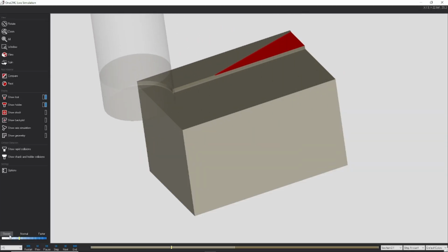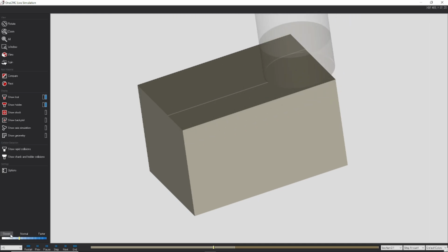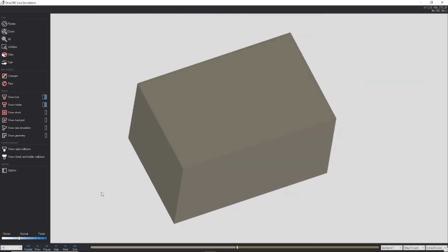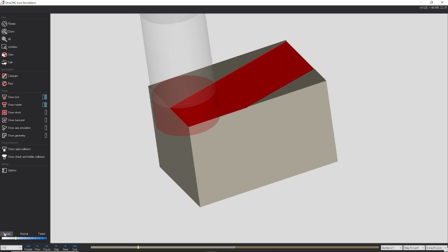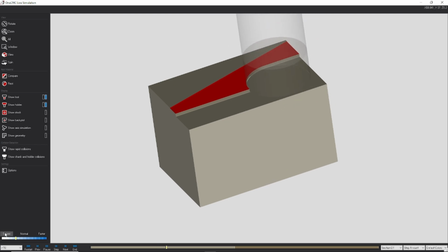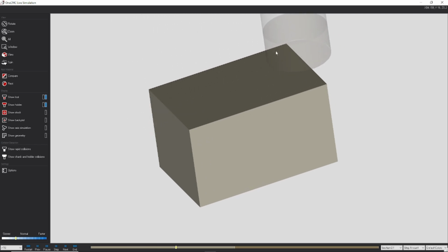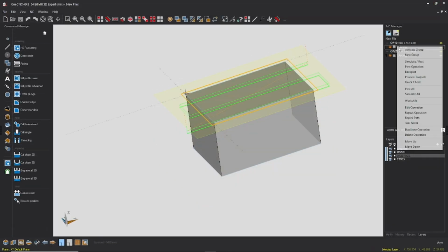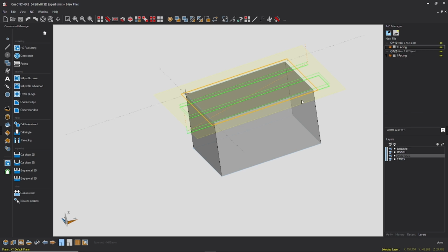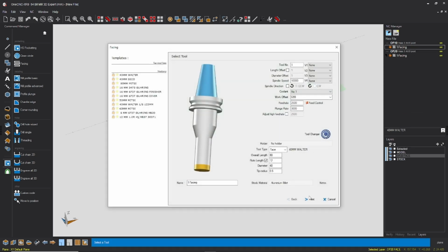Well, that's not too bad. Right, so let me restart that and show you something. So watch, I think there's a lift in here. Yeah, look there. See how it highlights it as red? That's because I've set my Z rapid plane to 2mm, and my stock is higher, so let's not go any further. I know I've rushed through all this, so that's why.